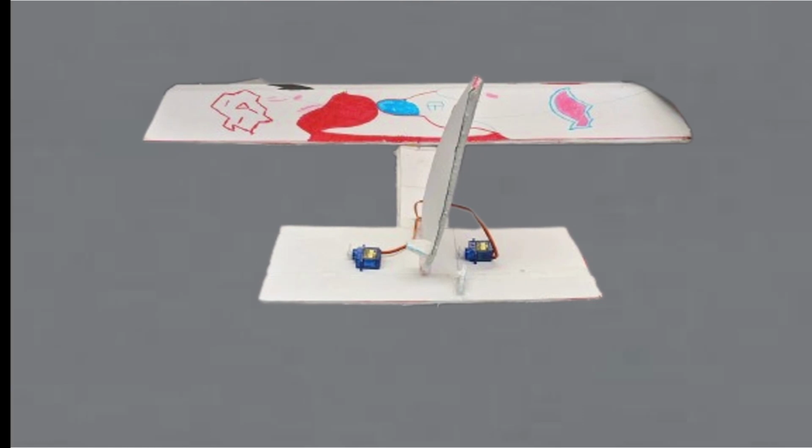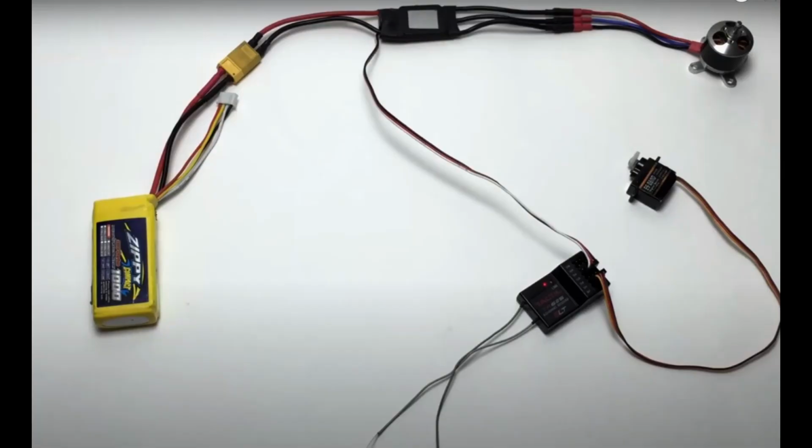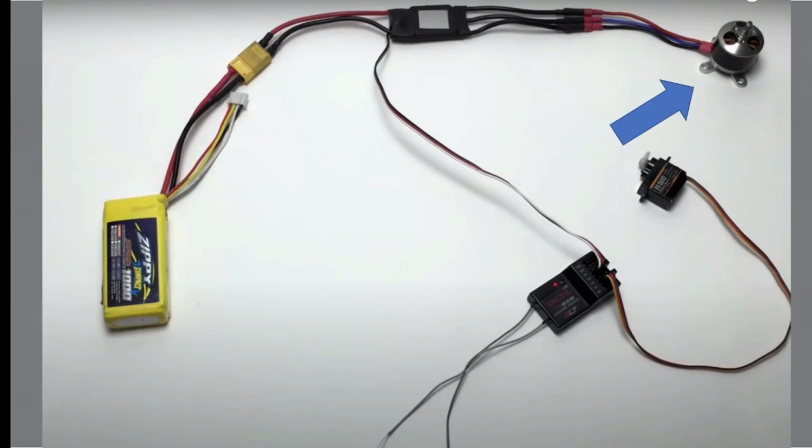To make the plane go up and down, planes use a horizontal flap, or flaps, called elevators, which we only had one of. The elevator is also located at the back of the plane, right underneath the rudder. The electronics in the plane were pretty simple. The main motor, the one at the front that spins very fast and had the propeller, was connected to the speed controller, which is pretty much the brain of the motor, which was connected to the battery and the receiver, which receives the commands from the controller and tells the motor and the speed controller what to do. The receiver was also connected to the two servo motors to control the flaps.